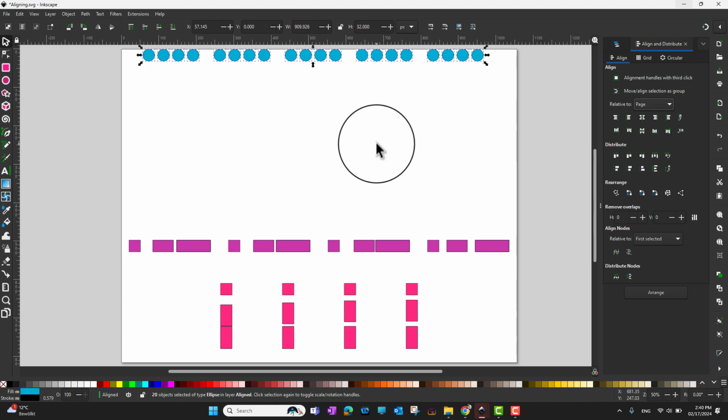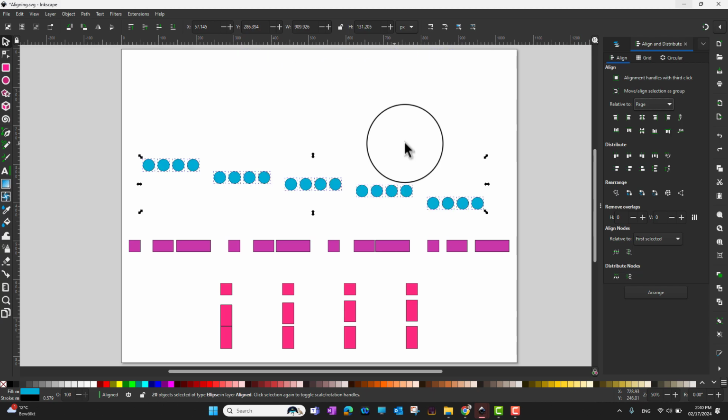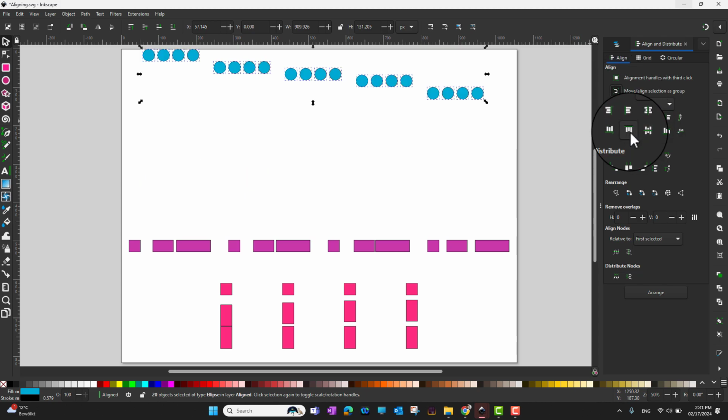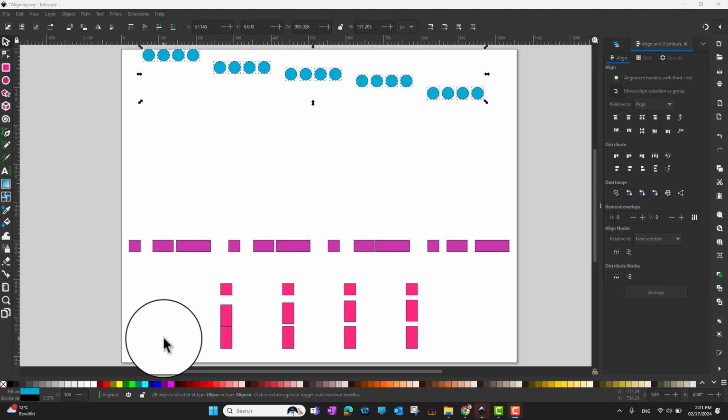So I'm going to press Ctrl Z to undo it. So what I need to do is select this align as a group, and then I need to click this button. So you can see now as a group, they have spacing and relation between them. They preserve that relation and spacing. This is what I want. So to conclude, we already have seen in this video that there are a lot of ways to control the positions of the objects in the align and distribute dialog in Inkscape.